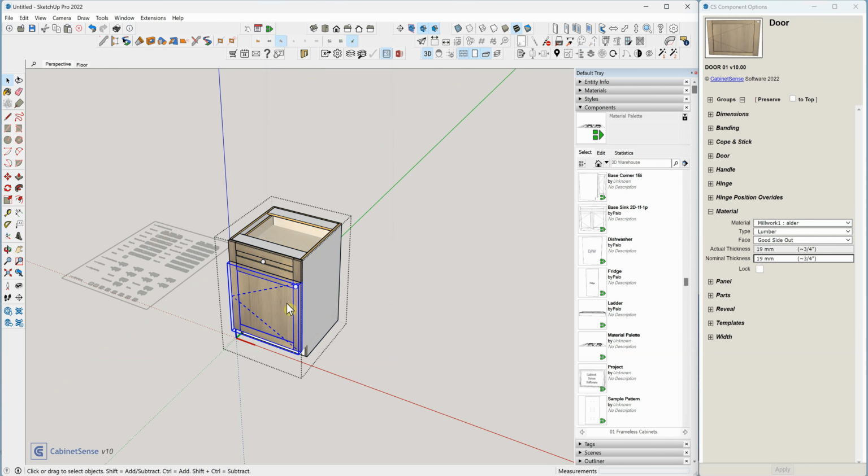I'm just going to make a copy of this cabinet. I'm going to change this to be 16 millimeters. And now let's call up our job material screen. And you'll notice we've now got 3 variations of thicknesses for our sheet goods. So this will allow us to do a quick review on the materials that we want to use and spot anything that doesn't look quite right.